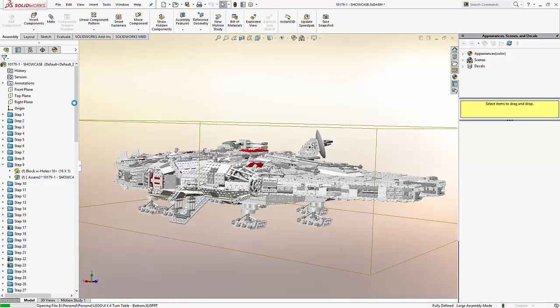One of the things that I've done here is that there's kind of two modes of thinking, especially when you start dealing with large assemblies. You can bring the parts in, put them where they're supposed to be, and tell them to stay there by fixing them in space, and then you can get rid of all your mates. Don't do that. The other way is bring them in, mate them in, but then fix them in space. Now, the cool part is, and I don't know when SOLIDWORKS did this, it was around 2012, 2011. They made it so if you fix a component with mates on it, it would suppress the mates on the part.